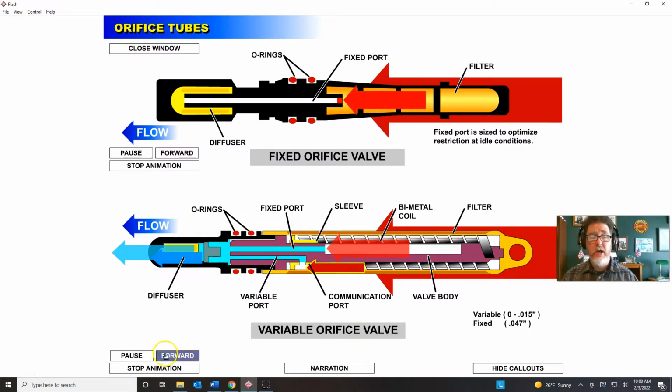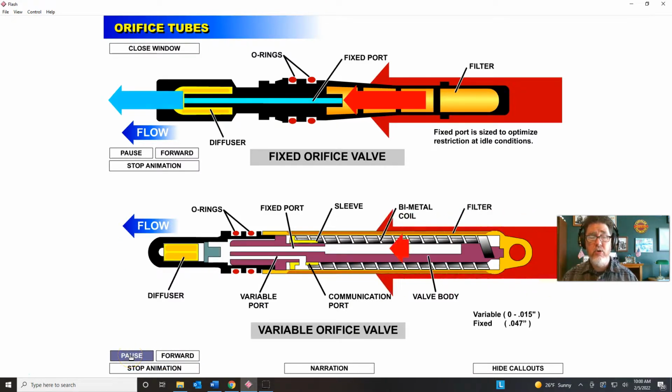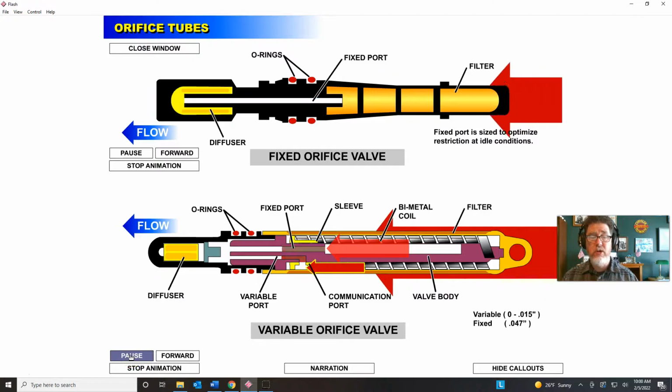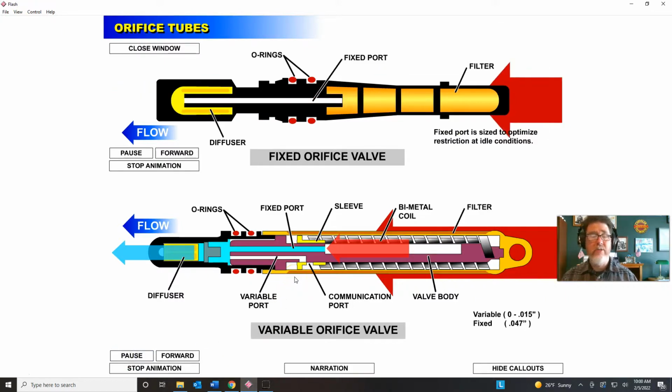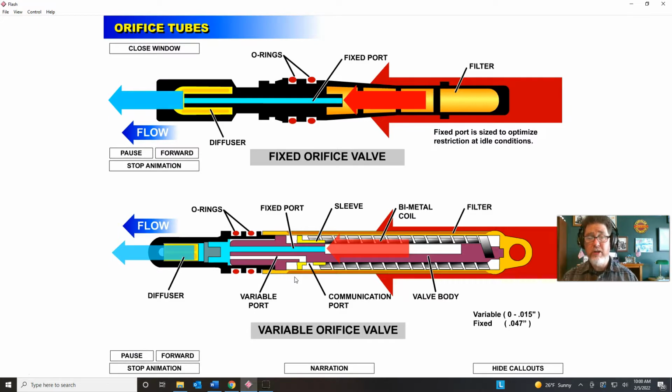But as the pressure goes up or as the temperature goes up, it's going to close, which is going to allow that refrigerant to evaporate in the evaporator just a little sooner as it goes into the evaporator. And again, why? Because the evaporator could handle it. There's enough heat load to ensure that all the refrigerant is evaporating in the evaporator, and my compressor runs continuously, and I'm not getting all types of cycling.